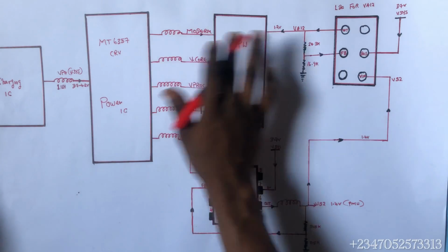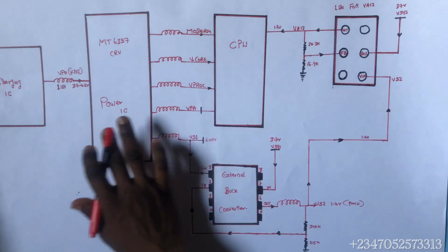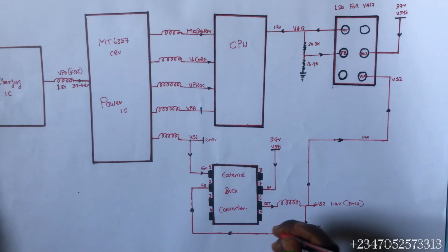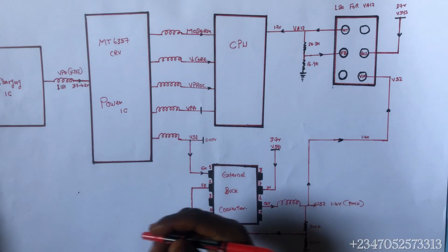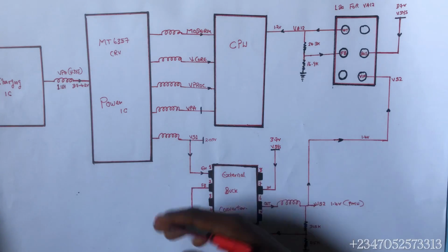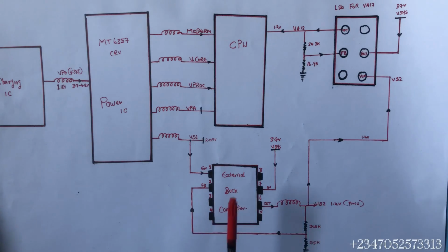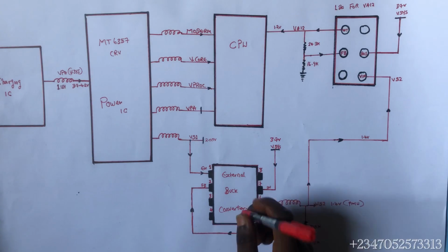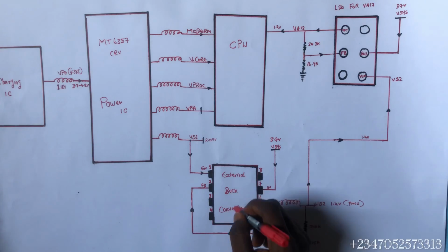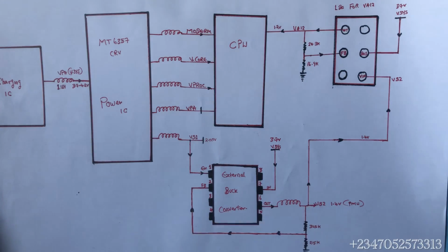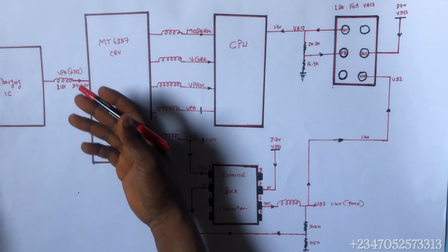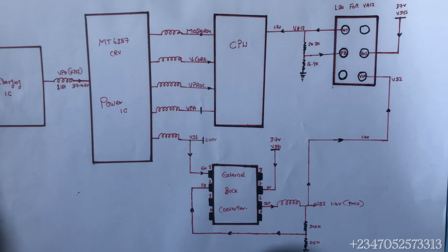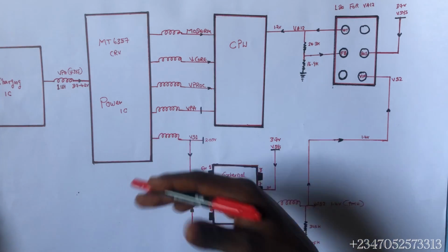So you start from the first line and then trace it one after the other until you locate that line that is having the fault. Number one, that line might be having a short. Number two, it might not have a short, but maybe the voltage on that line might not create, or it might not generate. So this external buck converter is one of the lines, according to our boot sequence, that could be faulty. If this line is faulty, the rest of the lines after it will not work, and then your phone will not turn on. So the DC supply might give you readings indicating that this line is faulty. It might change readings, so you don't have to focus on DC supply.